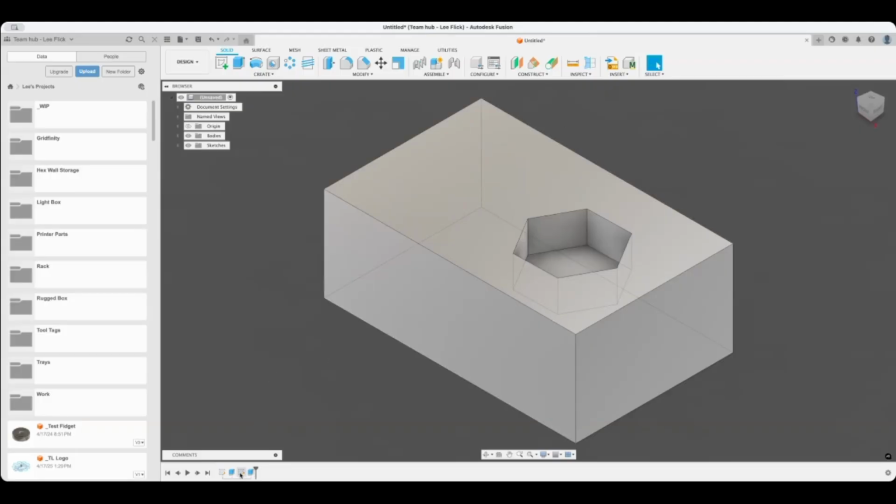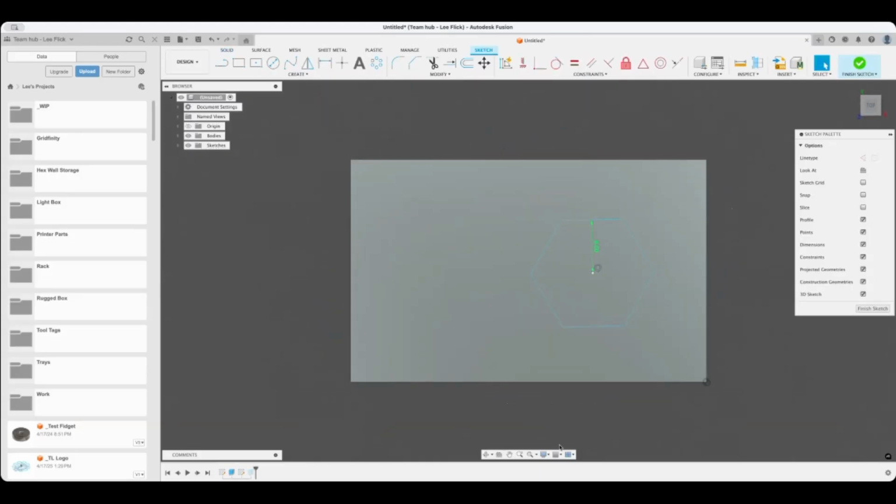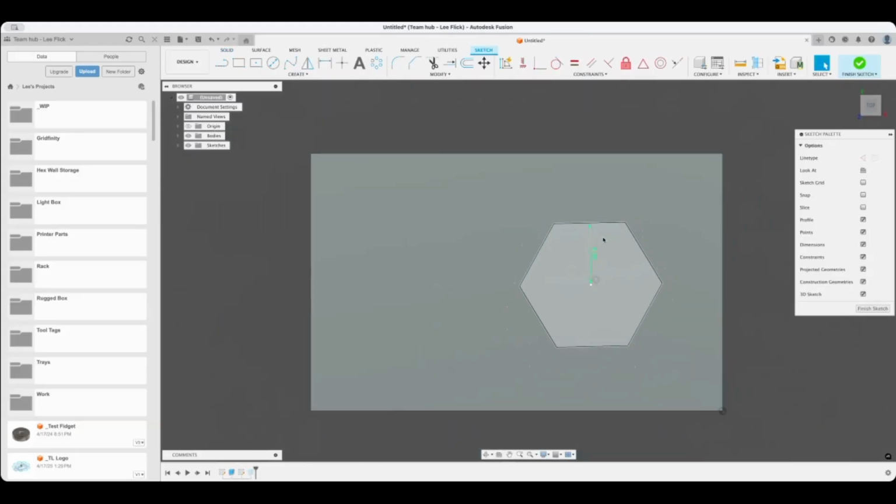All right. Okay. Now, if you go down below to the bottom, we got a sketch, extrude, a sketch, and an extrude. We're going to go to the second sketch. Now, if you look as I mouse over, the extrude's highlight. But let's double click on the second sketch. Okay, so let's center this hex. We need to know what the size of our block is.